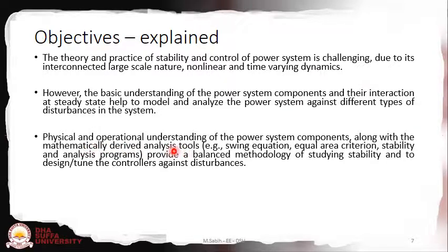Now this is the addition, in which we will focus and utilize the swing equation, equilibrium criteria, stability and analysis programs. They will help us to provide a balanced methodology of studying the stability, and that will enable us to design and even tune the controllers against different disturbances. So this is an integration of the basic concepts and the practices.